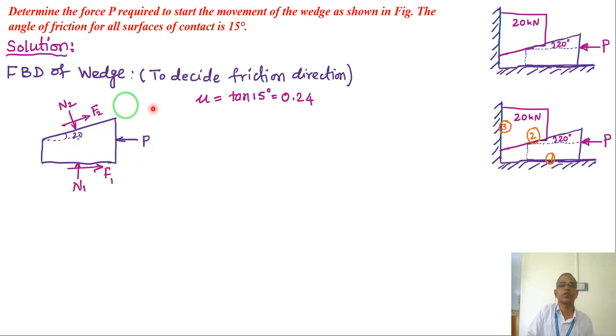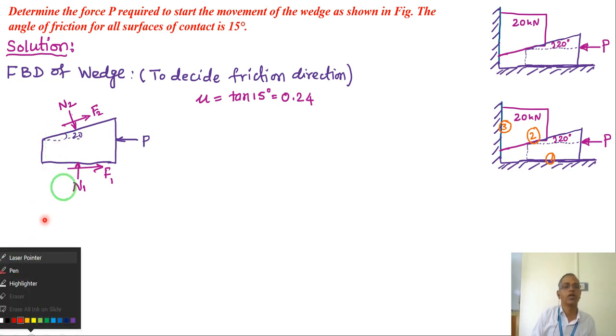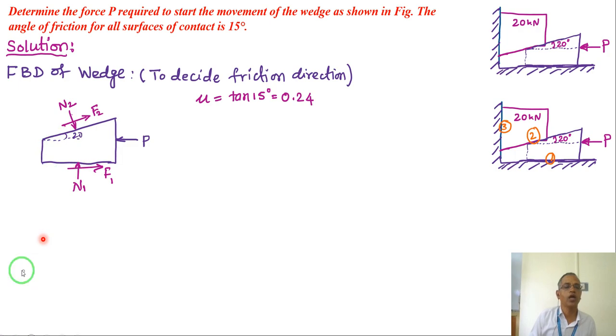Then between the contact, the inclined surface, the normal to the inclination is N2. The block is moving left hand side, the friction force is right hand side, F2 is upward along the surface always. Now this block has 20 degrees, so I draw a vertical, because I need to know the angle of each inclined force. F1 and N1 are not inclined, not a problem. The problem is with these two. So look at F2, which is along the surface.